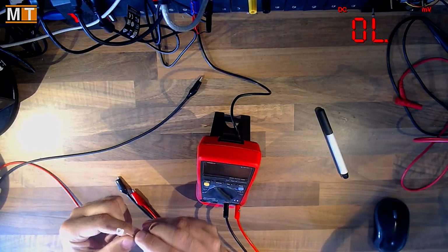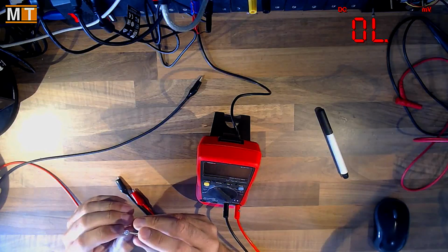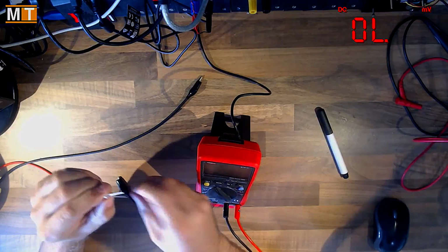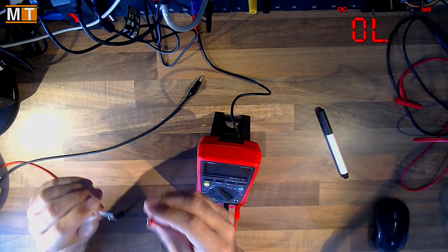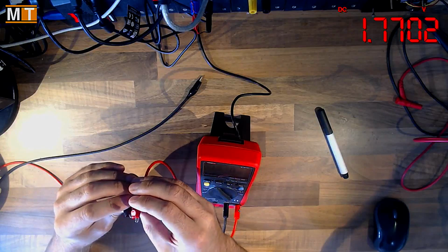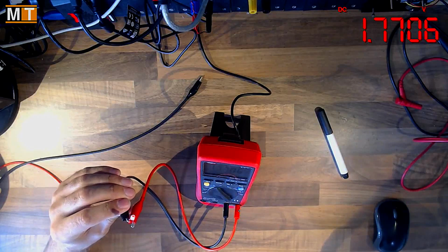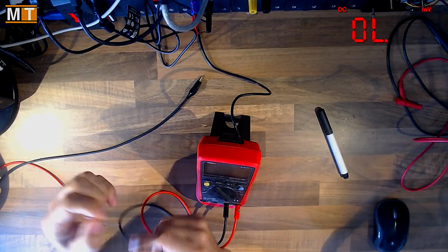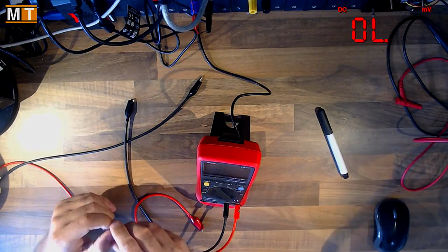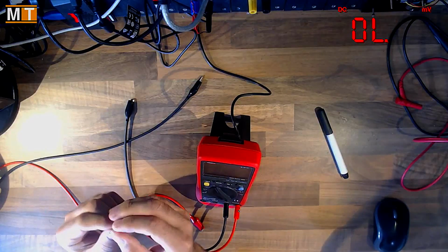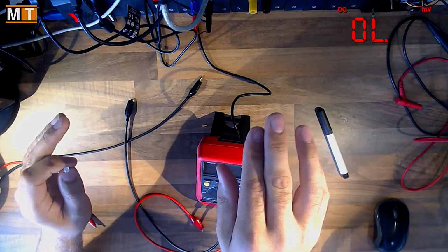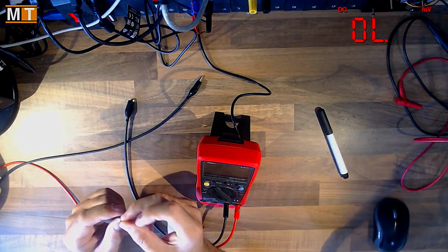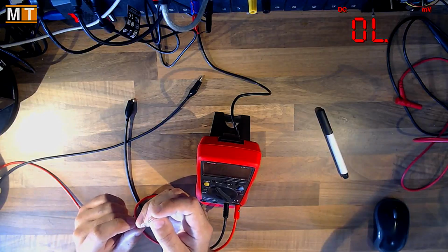Now, one thing to remember with LEDs is they are polarized components, so you have to find the positive and negative leads. Usually the flat edge of the LED, which is the shorter lead in this case, is the negative. So I shall connect negative and positive. The LED lights up and we get 1.77 volts across there. So the forward voltage of this LED is about 1.7 volts. That's at a very low current. I could work out the current, but I can't be bothered right now. We don't need to know. That's the point where the curve on the graph starts to shoot up. So for proper operation of this LED, we shouldn't provide any more than about 1.7 volts across it. And that's the critical thing.